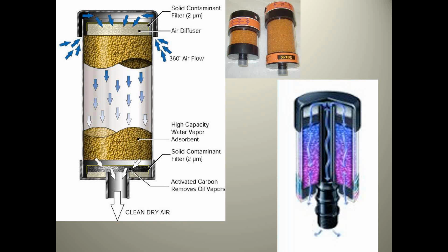We talked about our desiccant breathers. And again, these work very well. You should have some of these on any equipment that's getting moisture in. But you can see the Air Sentry model on the left, the moisture comes up through the top, goes through a dust filter down through your desiccant. But if these get completely saturated, and I've seen these so saturated at facilities that there'll be mold growing inside of them, that moisture goes right into the unit.